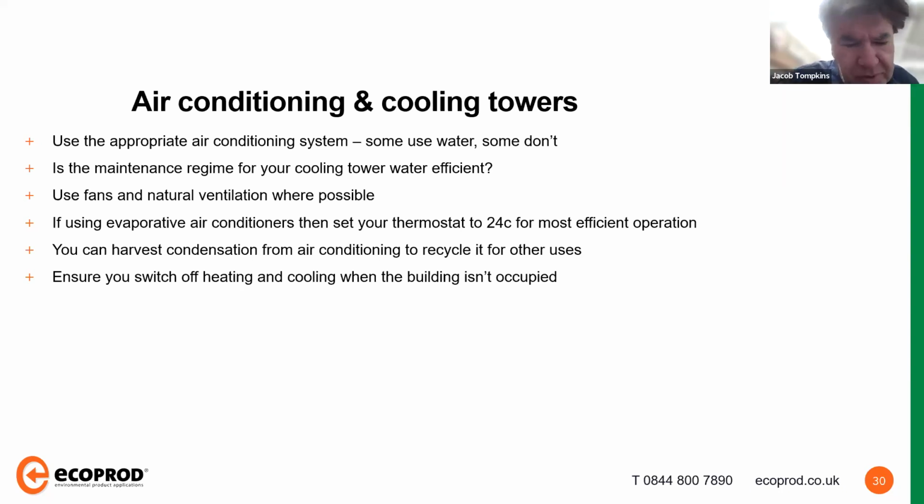Yeah, I think one thing to talk about is that quite often cooling towers have a set cleaning regime. So once the total dissolved solids hit a certain level within the condensate and the concentrate, the water's discharged. You can optimize that. So instead of having 3 or 4 cycles of water, you could probably up that to 5 or 6. But you need to look at it on a site-by-site basis. Quite often, there's a lot of caution and a lot of safety built into air conditioning and cooling towers, and you can adjust that. But obviously, in this case, and there's a question on hygiene here, hygiene comes first.